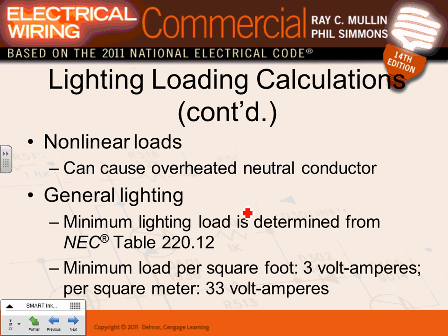Did you guys hear me? A 225 amp panel, equal or less than this, go full neutral. What's the problem with harmonics? Harmonics go in the neutral and they burn the neutral. They don't add up to zero like everything else. They are the offenders, the bad boys and bad girls. So they don't add up to zero.